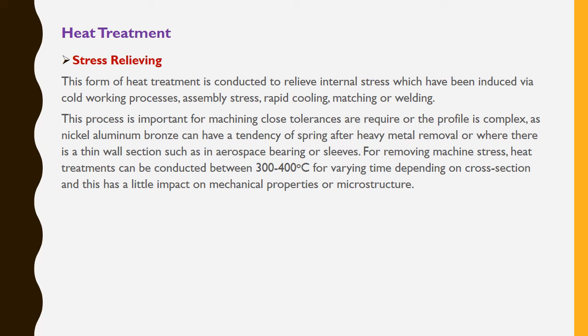This form of heat treatment is conducted to relieve internal stress which has been introduced where cold working processes, assembly stress, rapid cooling, machining or welding have been used. The process is important for machining where close tolerances are required or the profile is complex, as nickel aluminum bronze can have a tendency to spring after heavy metal removal or where there is a thin wall section, such as aerospace bearings or sleeves.